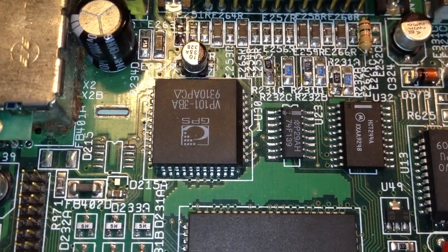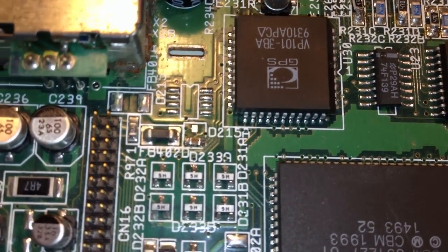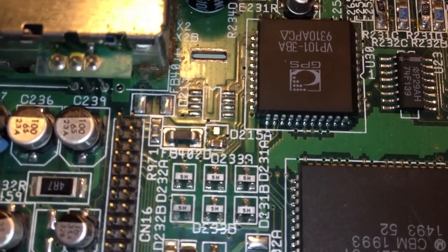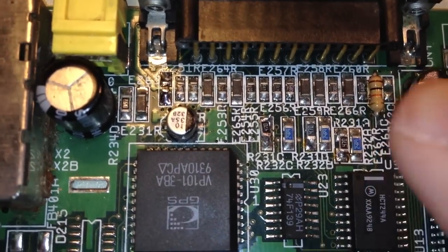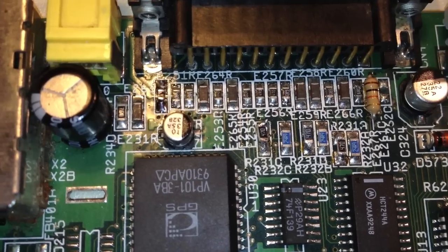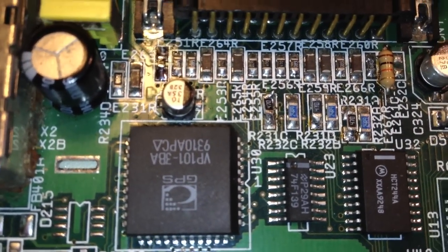Interesting. The capacitor I temporarily borrowed is back again on my motherboard, but here we're looking at the motherboard I'm currently working on, and we can see that I got the new capacitor in place there, and everything seems to work just fine. So now I just have some additional cleanup to do, like resoldering some components here, removing this resistor and putting a suitable SMD component in there. But after that, I'm basically gonna be done working on this motherboard.